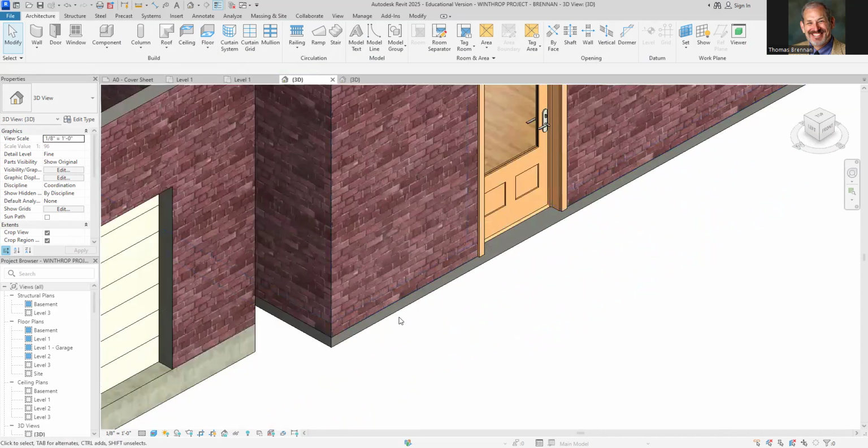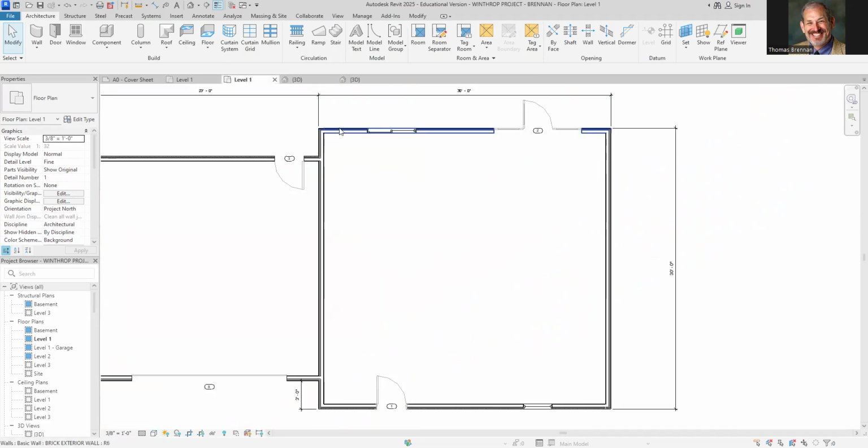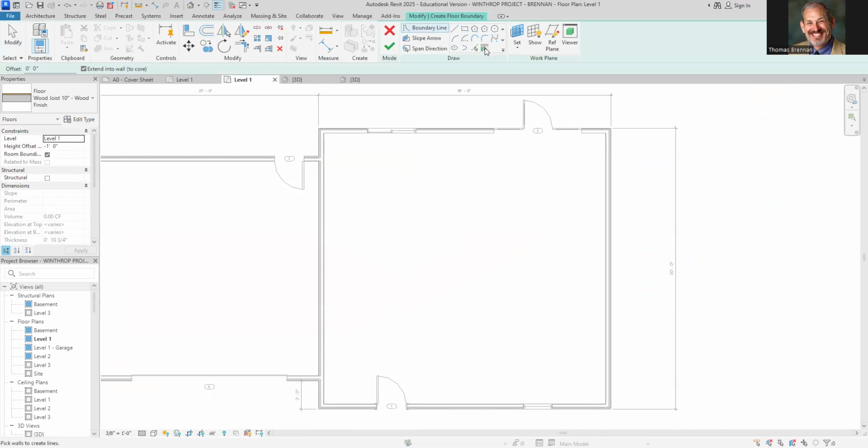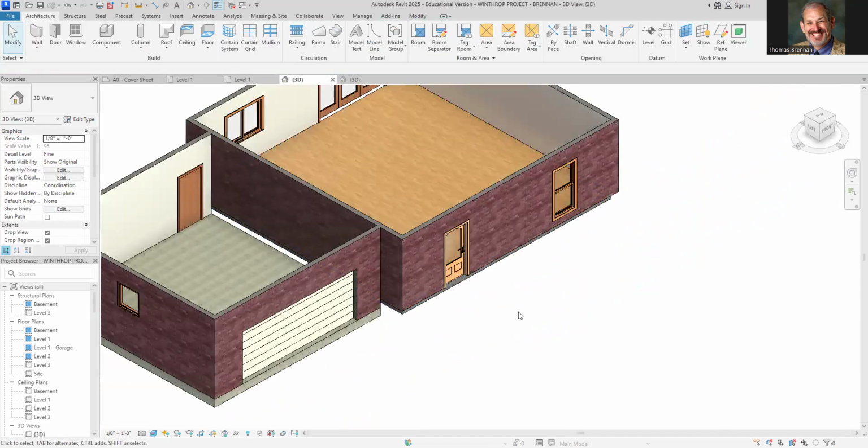But yeah, again, I didn't go to the inside, so I'll do that one more time. All right, one more time. I'll go to floor, and I'm going to go to the inside walls. So inside walls, all the way around. And again, what I want to do is make sure I don't use a negative 1 foot height offset. We'll make that 0. And we'll hit the green check mark, and we are good to go. All right, looks like that.